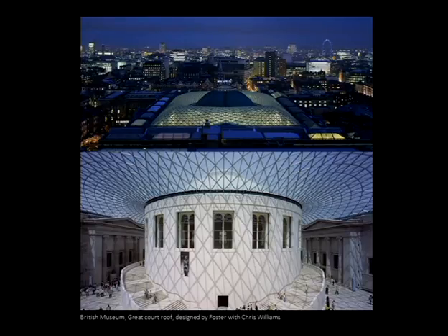There is no bending moment at all, and everything happens in plane, so only in-plane stress. So it's very lightweight. And this is all triangulated because with triangles, the glass panels are planar. If we have squares or quads, they can be doubly curved, so the glass would be very expensive. So they're all triangulated. And I'll explain in that lecture a little bit how to do that, or at least what that means.